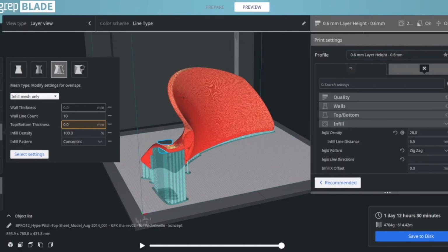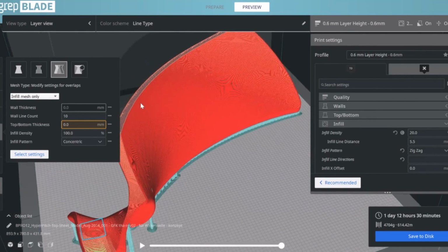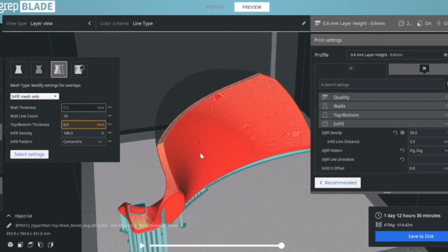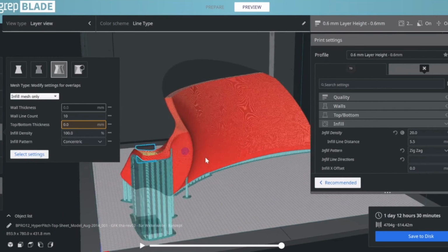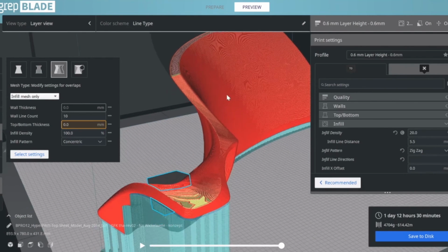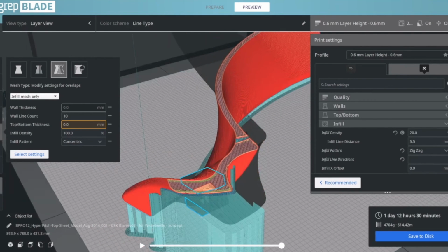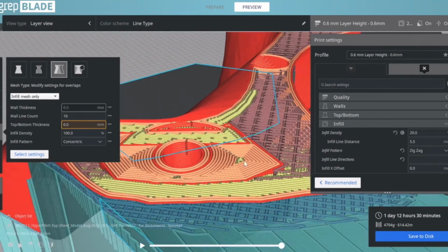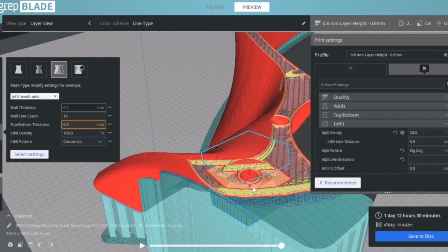Okay, as you can see, the propeller is fully printed, 1 day and 12 hours. I can go through it and show you the infill density is at 20% with a suitable pattern, but now I'm going to look at the infill density of the cube itself, which was set to 100%. Fully infilled area around the holes in this way. So I know that my plastic is fully dense in the area where I need it to be strong. That's another very smart use of this feature.